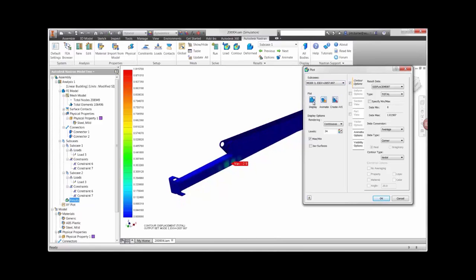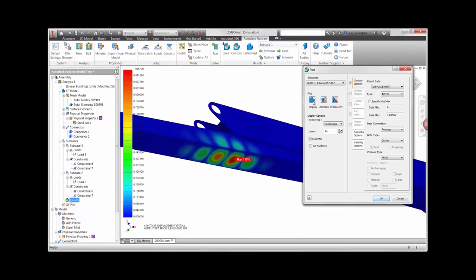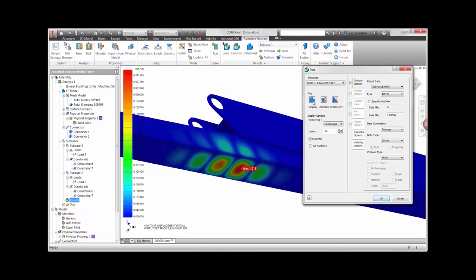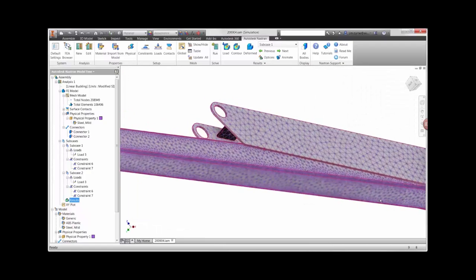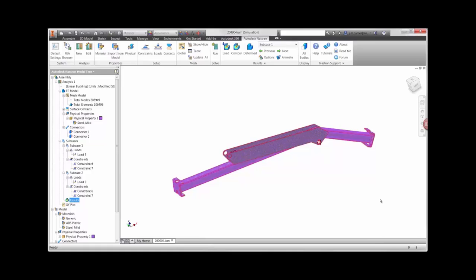Since we wanted a minimum of 20,000 newtons, this is clearly a problem, and we may want to make modifications to the model dimensions to avoid catastrophic failure for larger loading conditions. This workflow not only saves time and money during the design process, it also ensures a safer product and fewer warranty claims for the customer. Autodesk Nastran In-CAD helps to make better products using digital prototyping.